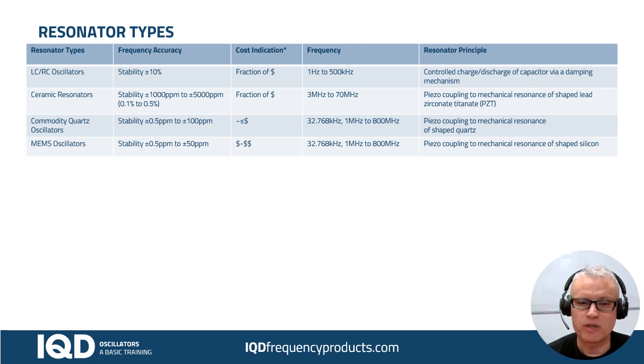Maybe one of the main differences between a MEMS oscillator and a quartz oscillator is that the MEMS resonator system will have one frequency that it resonates at, and then there'll be a PLL circuit that's shifting that into different frequencies, whereas with quartz you tend to grind and lap and polish the quartz to make a specific frequency from that. So the main reason why the two might differ would be the phase noise. On a phase noise plot for a MEMS you might see a bit of a hump caused by the PLL circuit, although I have to say they've got very good over the last few years, so they're not such a problem as such anymore in the applications they're used for.